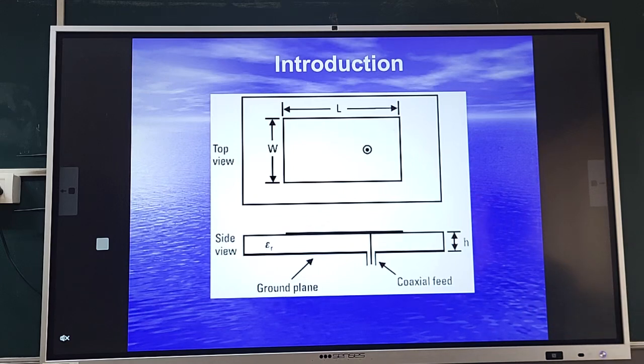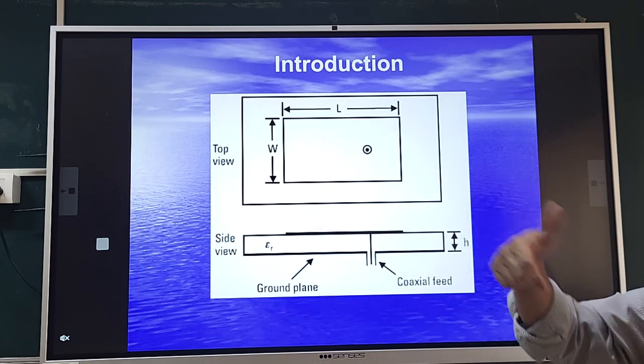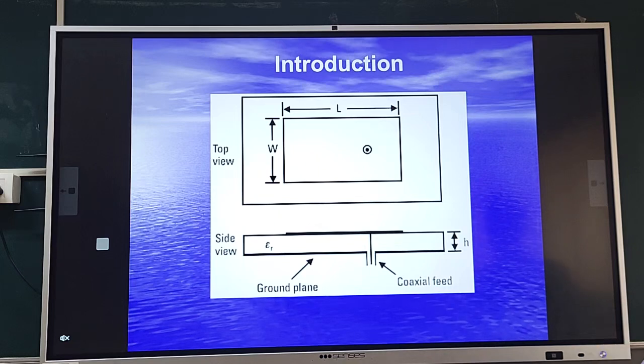When you go for a sample sheet, different variations are there, whether you select an RO substrate or an RT substrate. What makes the difference is the dielectric constant. One has 2.33, another has 3. So that is the difference with respect to the substrate. Another substrate is Arlon. Another substrate is Teflon. So these are different substrates which are possible.